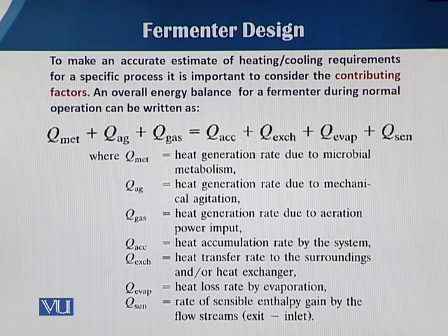So in this slide, we can easily understand the different contributing or disturbing factors of the temperature in a fermentation vessel. Here you can see the equation: Q met plus Q Ag plus Q gas is equal to Q accumulation plus Q exchange plus Q evaporation plus Q sensible.